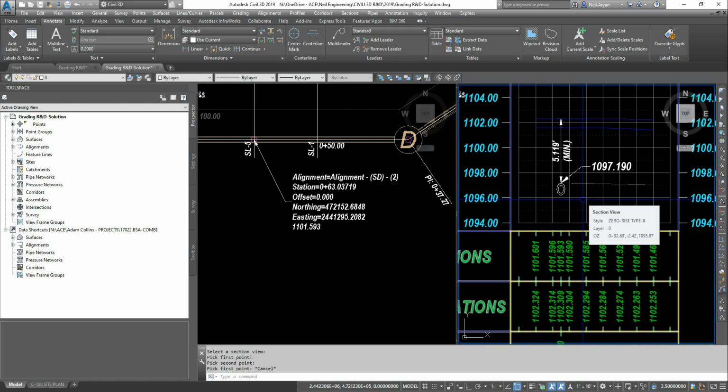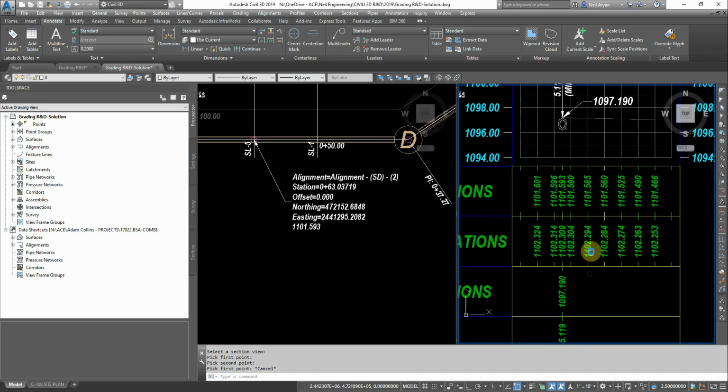So this is the method. We can also use the same for the water pipes and also any other utility pipes, not only for one pipe or single pipe or double pipe. So wherever you have a multiple number of networks running parallel to the alignment, just make sure you have an additional vertex point where a pipe is exactly cutting on the sample line. If you have those vertex points, just turn on and add the appropriate content, and then see all the information as you want. So that's about the session.